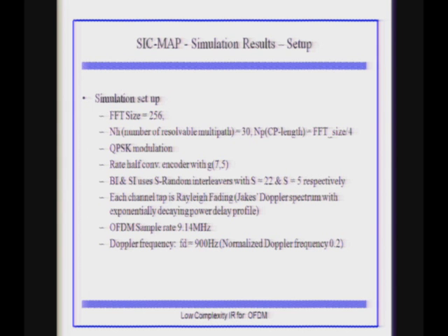So the quick question, does that introduce some kind of delay or coding? Definitely they do. And that's one of the issues of turbo equalization. With this, the higher this S, the higher the delay we have. And once you have a higher delay, you have more randomness in the data, but when your application is really delay sensitive, you cannot go for such interleavers.